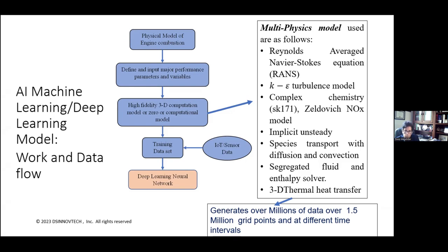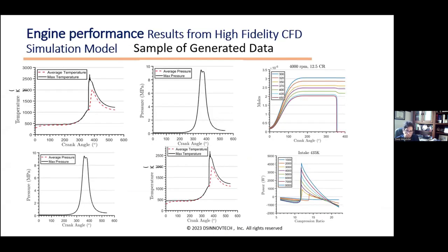So we use that. And this is a sample of data that shows, during the run of the engine, the crank angle, temperature, pressure, and the number of moles of species formation that is taking place, and the temperature that is peaking out. You can see that on this figure. This is the start point of the ignition, and the duration is a short one. Actual combustion is taking place, and the whole focus is around that, because this is going to control the temperature and how fast it is. It will control whatever performance you're trying to achieve, the losses and the NOx formation.